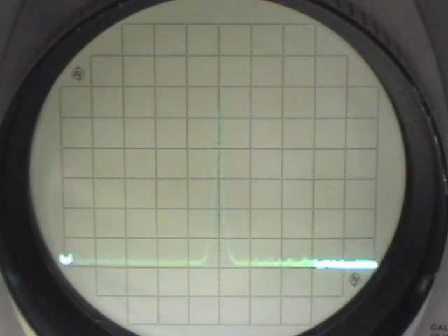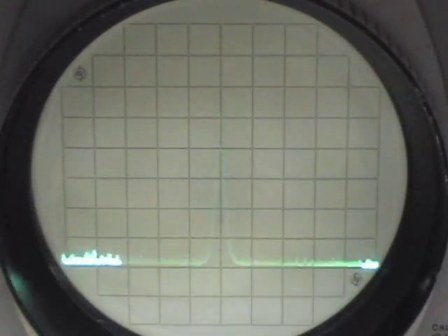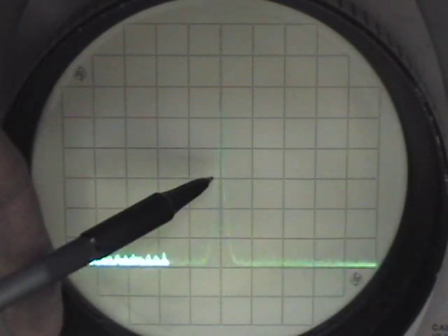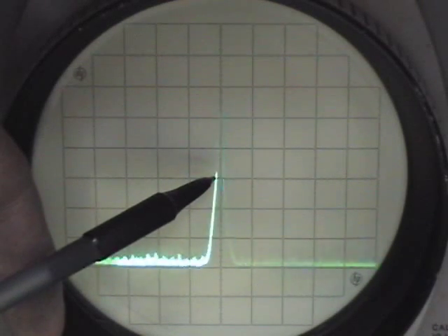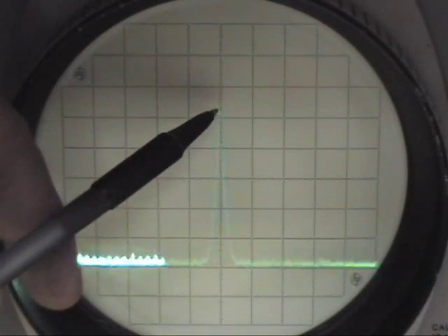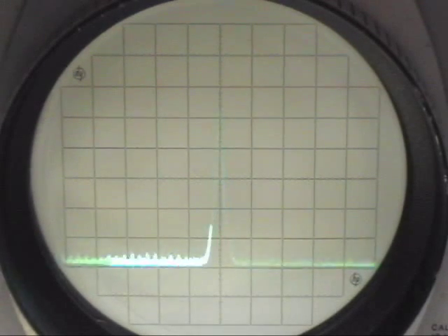We've made the switch, and if your memory works for you, you remember that we started right here. This is what the input to the amplifier was, so we've got 10 dB, 20 dB, about 3 more dB there, so it looks like we got about 23 dB of gain through the amplifier.